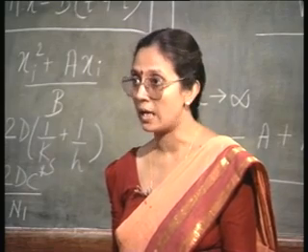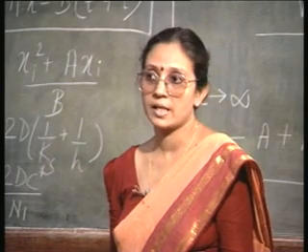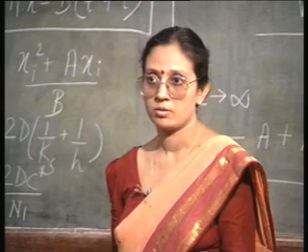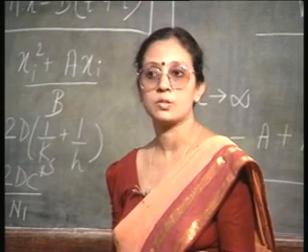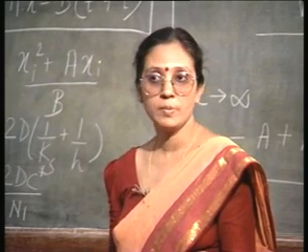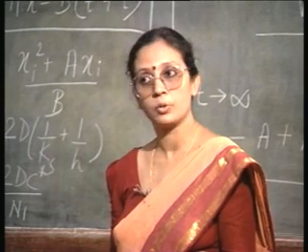And that is what is done actually when you need thicker oxide for masking or for field oxide, then you use wet oxidation. On the other hand, dry oxidation quality will be much better, we will discuss that later on. Quality will be much better and I will have controlled thinner growth of oxide.